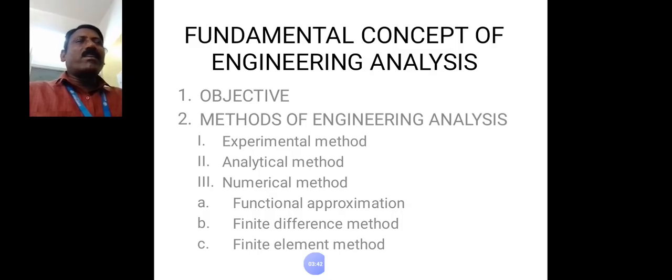This function has known parameters and unknown parameters; you need to find the unknown parameters with the help of the Ritz method and Galerkin method. Especially the Ritz method is useful for solving the complex structural problems encountered in finite element analysis. The weighted residual method is useful for solving non-structural problems.